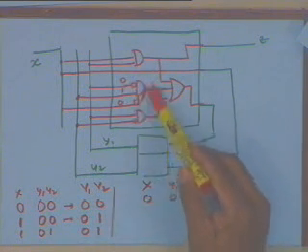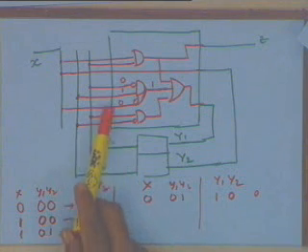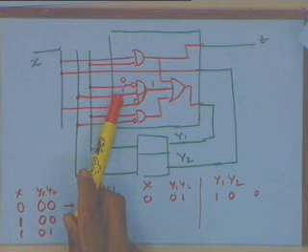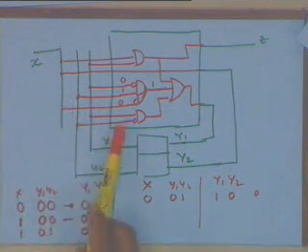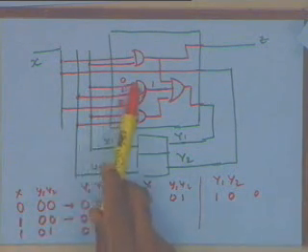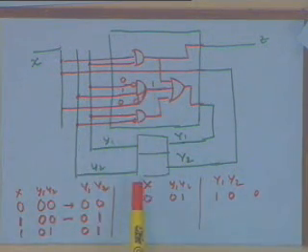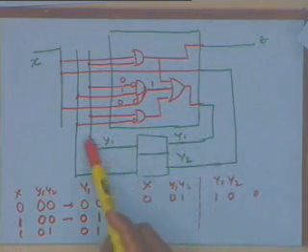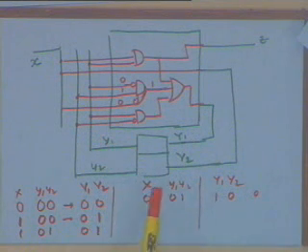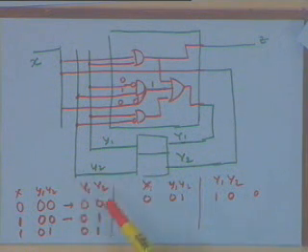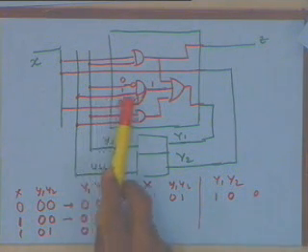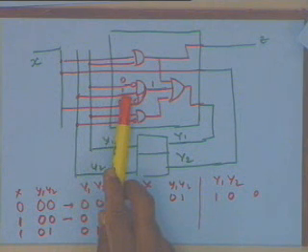If you look at this particular gate, x0, so if it gets the values x0, y2 1 and y1 0, these three inputs, all of them will generate this to be 1, and this one will hold on. How will it hold on? Of course, after a time delay d, y2 will become 0 because x is being passed on as y2. So this one cannot remain 1 any longer, it has to go to 0.